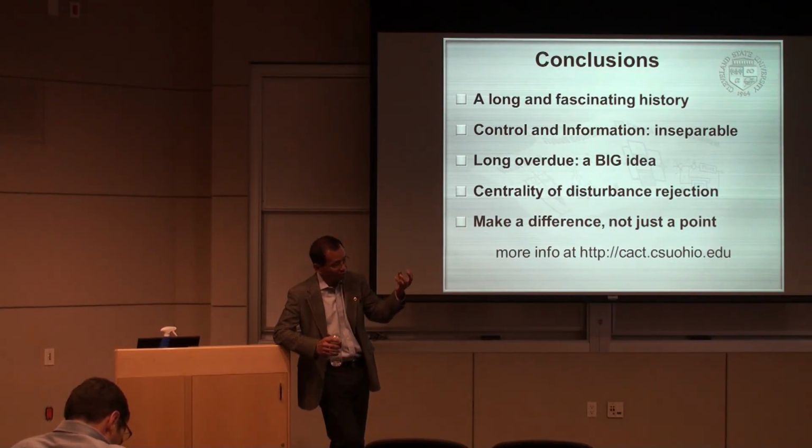You have a transfer function of the plant, you invert it to control it, but the plant drifts. So you use an adaptive algorithm to make real-time adjustments. So you follow the change. That's another type of intelligence.